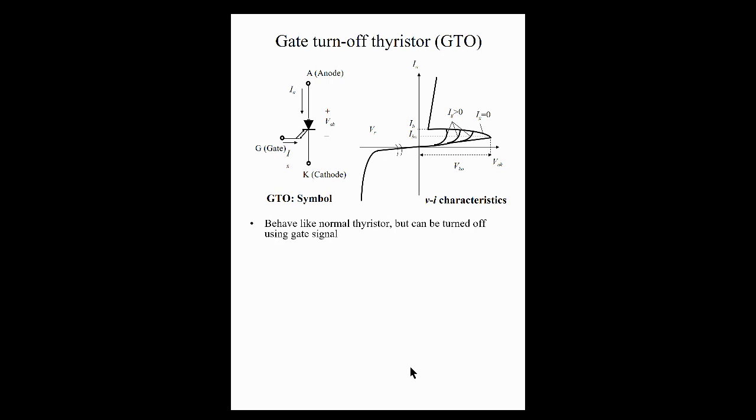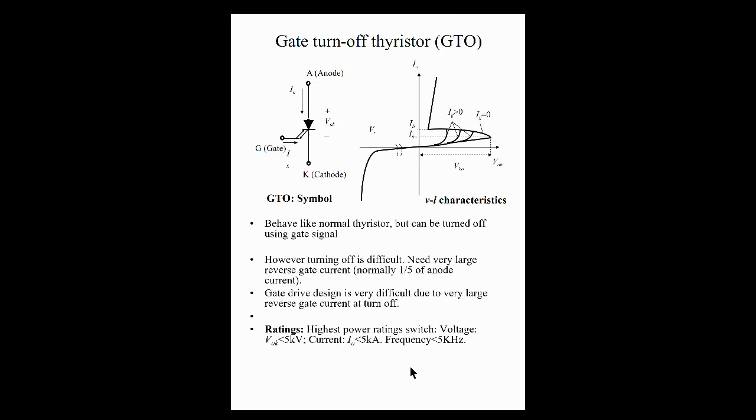So the SCR, that's a silicon control rectifier, as you can recall, when we remove that gate signal, it remained on, it was latched, right? Similar with the triac, we remove the gate, it remained on, it's latched, right? So with this device, we are able to control it from the gate, right? So it's very much similar in operation. The main difference is controllability at the gate.